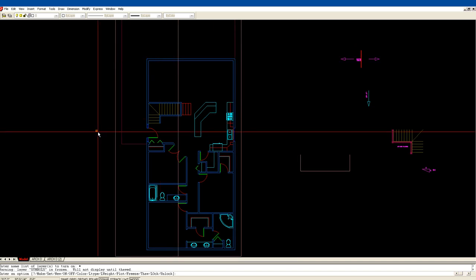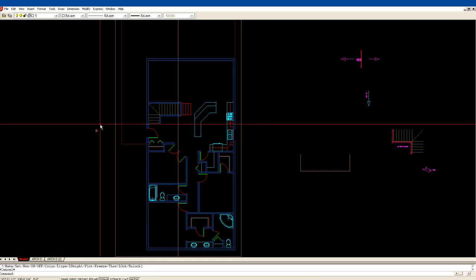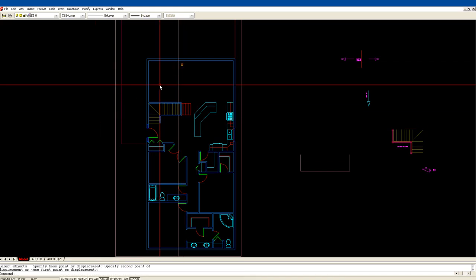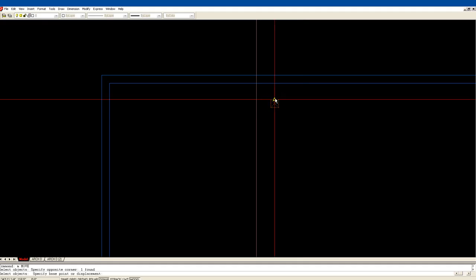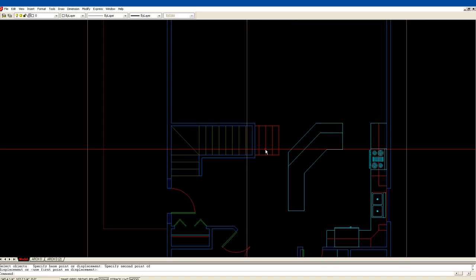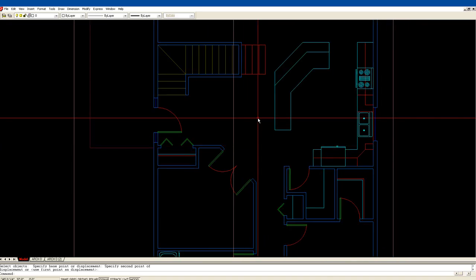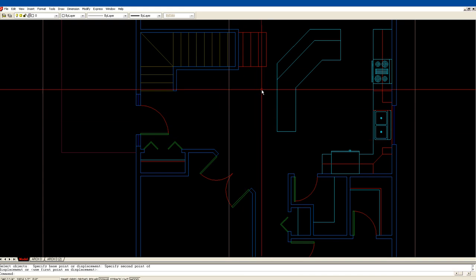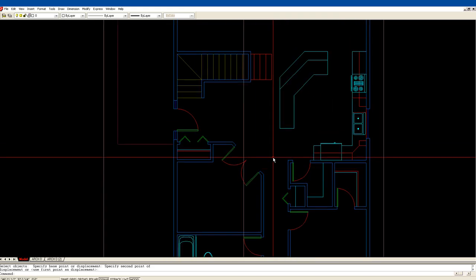I'm going to move this little guy closer. So I have a beam that's going to run right down here. We talked about it when we were talking about cross sections in another tutorial, that this is going to be an open ceiling with rafters at a 5/12 pitch, and the back of the house here is going to be a flat ceiling with trusses.